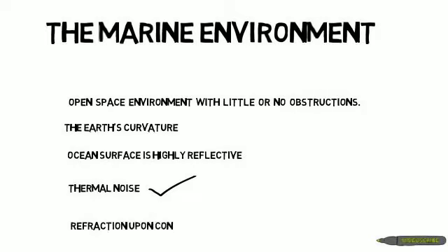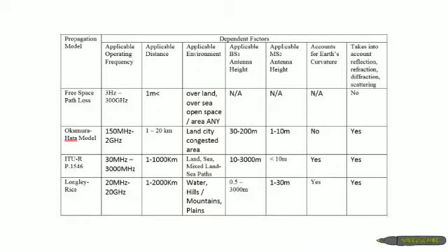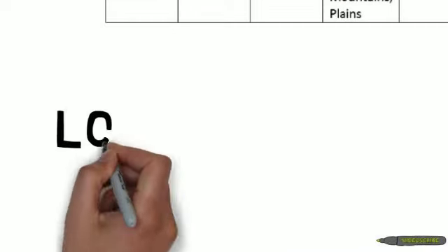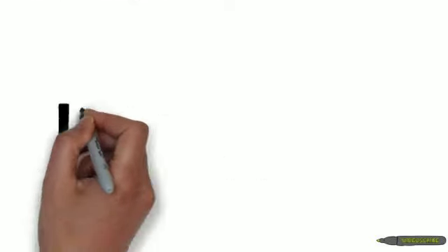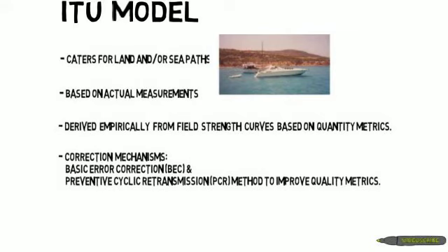Considering the characteristics of the marine environment, both the Longley-Rice and the ITU model were suitable for the marine environment. However, a suitable model was selected, this being the ITU model, as it was suited to the environment, and its field strength curves catered to the ever-changing marine climate.